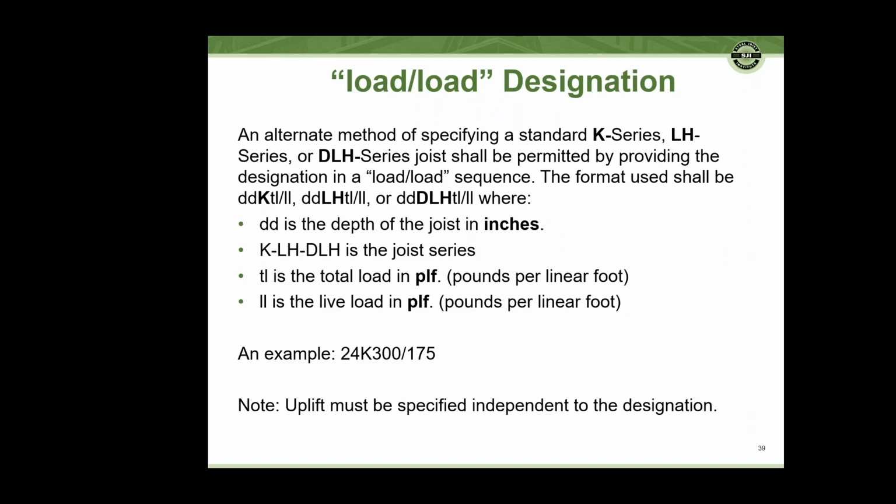Load over load designation. This is important and very common. It's called an alternate method. I'm not sure that's really the best terminology because, again, it's very commonplace. But the idea is that instead of picking an arbitrary chord number, we can dial in a more specific designation by prescribing a total load and a live load.